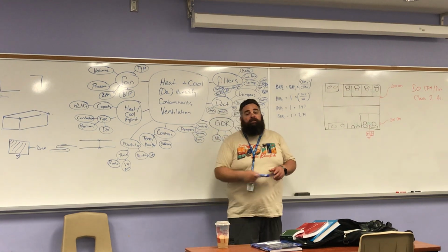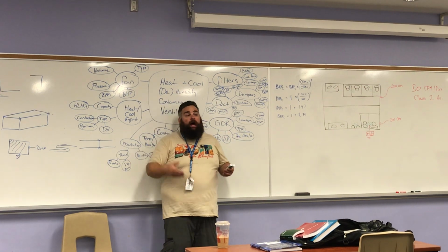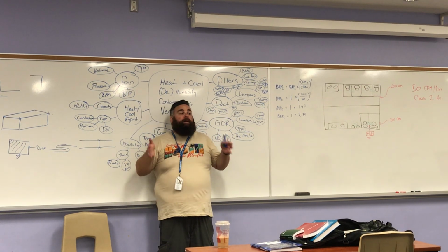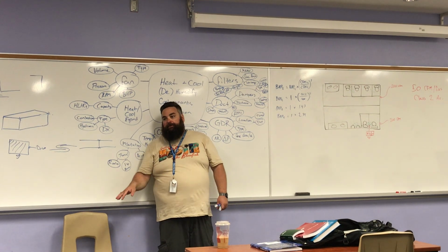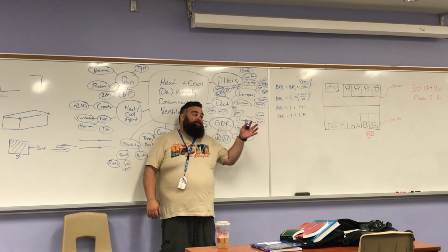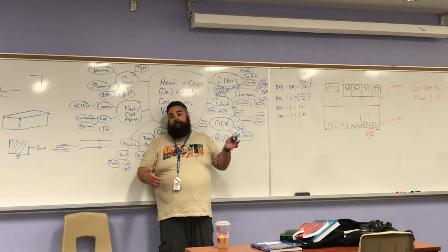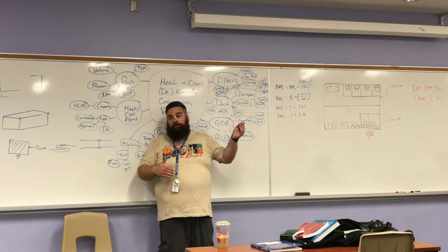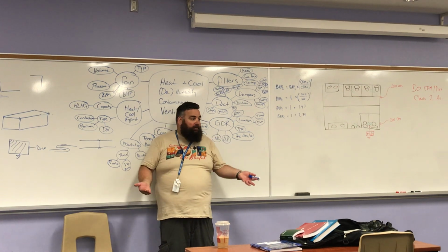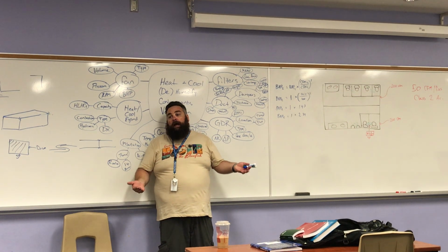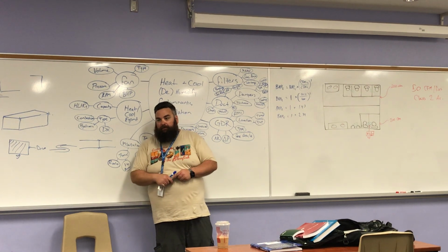And let's say the architect isn't against it. How am I gonna finish it? Am I gonna finish it with a big bulky weather hood, like I showed you, that hangs off the side of the building? Nobody likes the look of those. Am I gonna finish it with a more expensive louver? Well, louvers have a lot of pressure drop. We need a lot of free area, so it has to be bigger. Do we have structural concerns now? Do I have to put in a lintel to support that load? How do I make that watertight completely? These are all concerns that we factor in, okay?